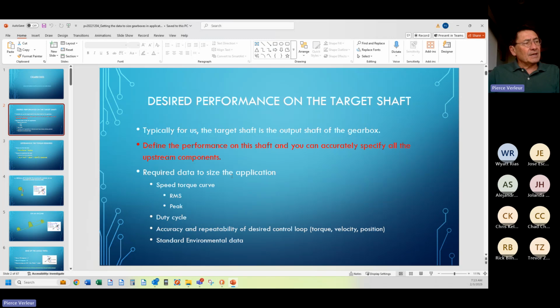That dial plate application, because it starts and stops, position is important. Torque and velocity can be important too, because we don't want to move so precipitously that we knock the bottles over. Yet we want to move as fast as possible to optimize and maximize production. But position. How accurately do we need to put that bottle in front of its station so it can be properly filled? Or the cotton stuffed in? Or the cap screwed on? Or the label affixed? We need to know that.